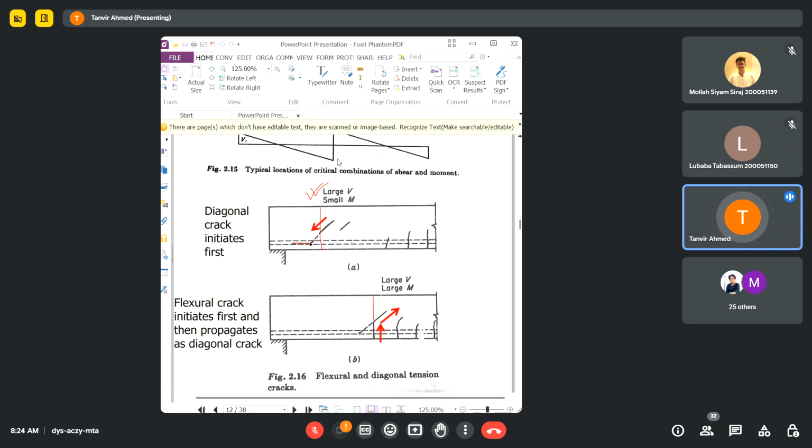And in the downward direction, if you have longitudinal reinforcement or main reinforcement, this crack will move near the longitudinal reinforcement, and it will become horizontal. So the crack near the longitudinal reinforcement will become horizontal, and it will not go further downward. This is because of the dowel action of the longitudinal reinforcement. We will be talking about the dowel action, and we will see it in a figure as well, inshallah.